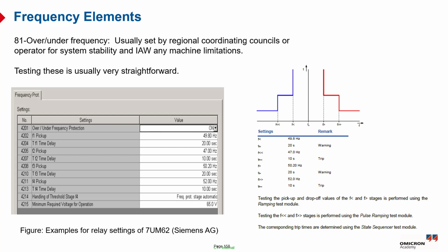In the hydro plants, the turbines can handle a wider frequency variation, so under frequency protection is often unnecessary, but the over frequency protection remains essential as a backup or to replace the mechanical overspeed devices in case of governor failure.